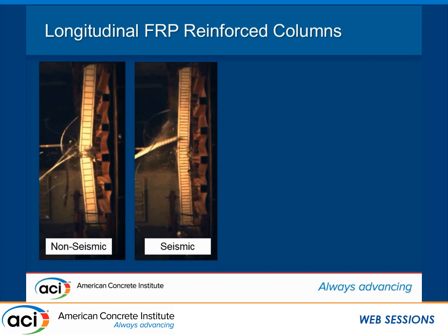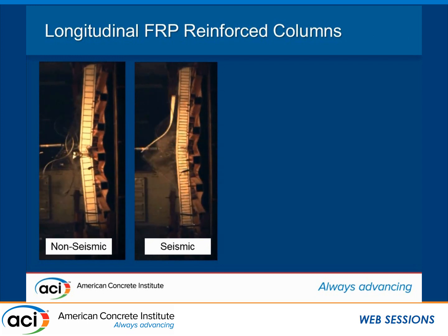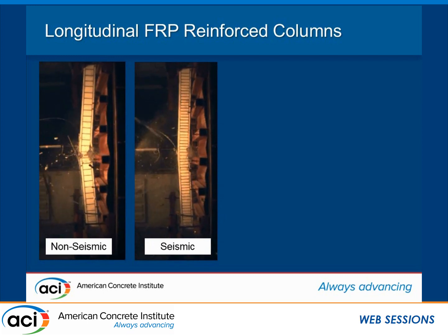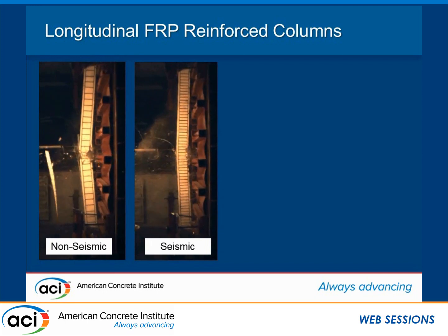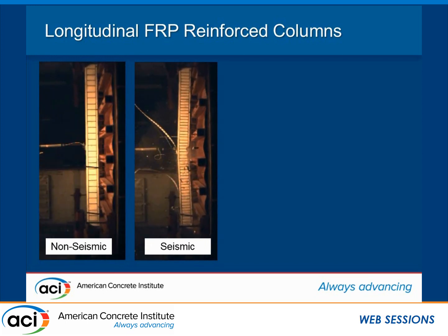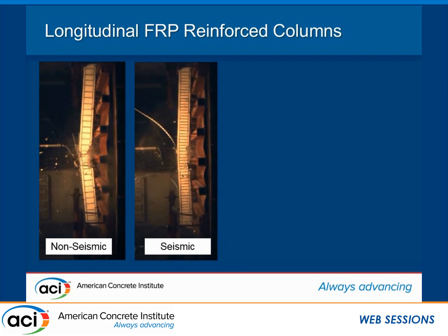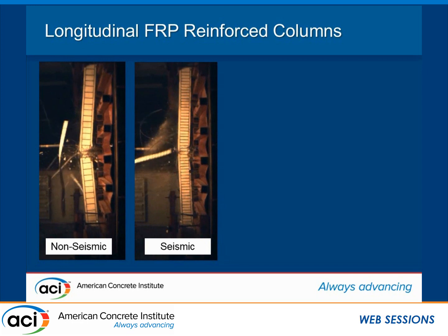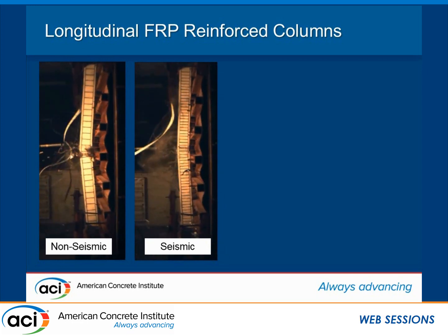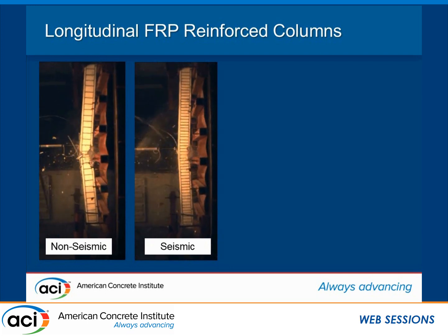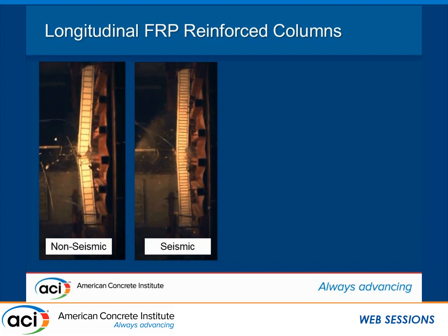By gluing or epoxying this FRP onto the surface of this column, and then taking into account that there is a moment reversal over the height of the column, so we switch from positive moment to a negative moment up here, we end up with a very high moment demand, and strain demand on the FRP at the top region here. We end up with a high strain demand in the middle at the high middle moment, and the effect is we end up with a significant debonding issue.